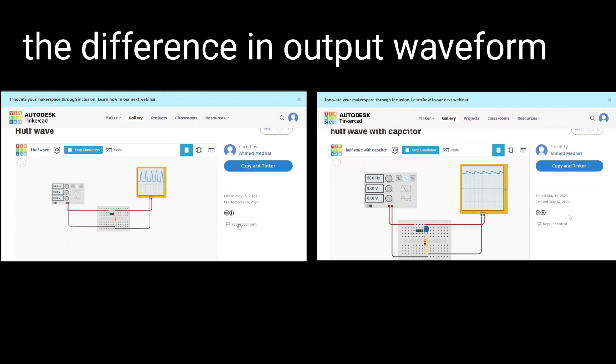During the negative half cycle, when the diode blocks current, the capacitor discharges through the load resistance, supplying current to the load. This discharge smooths out the output voltage.